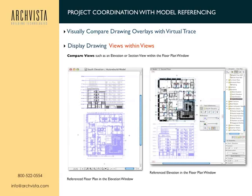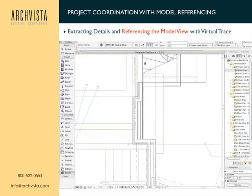But we are not just limited to floor plans within views. We can also view any drawing within a view. I can view an elevation, I can view a section, I can view details, I can essentially view any view within any view. As this example shows, I could open up my south elevation, and I could turn on my floor plan as a reference. So I can see that in relationship. Or I could be in my floor plan view, and I could turn on my ceiling plan, my elevation view, and see that as a reference. And again, the same thing holds true. I simply right-click that elevation, say Show as Trace Reference, and that will automatically show on this view. Here's an example.